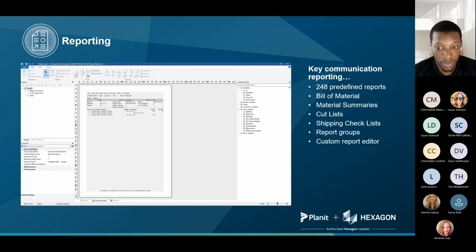You can produce this report with the report editor and then export it. You can even print it as a standard report, but you can also save it in different file formats: PDF, Excel file, even a text file or CSV file, for example, and then connect CABINETVISION to another software to read this file and use this information for your internal services.